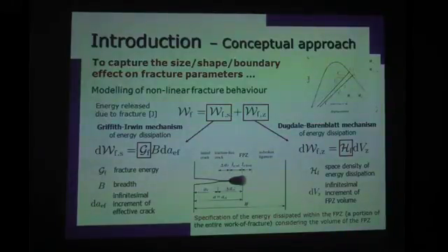We think that we can adopt a theory which would say that we have to separate energies being dissipated in those two entities: the fracture process, or the nonlinear zone, and the crack propagation, which is somehow sketched on this slide.